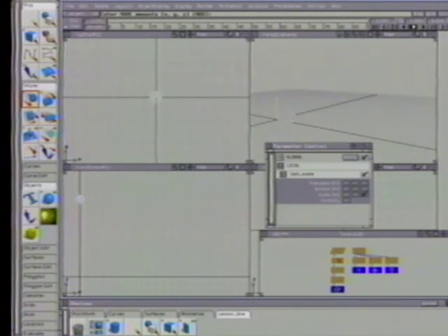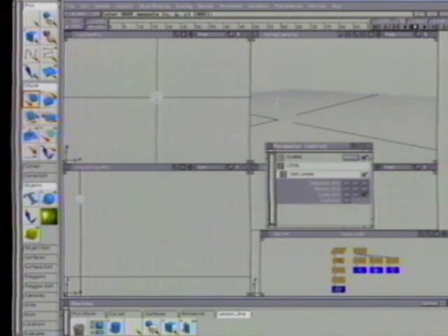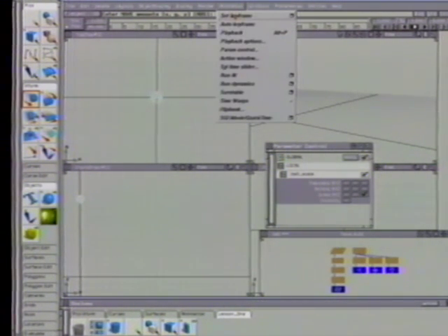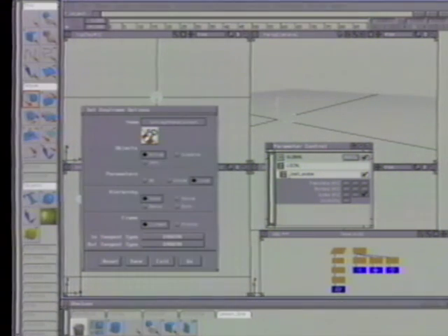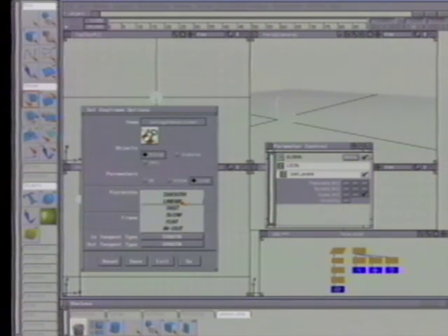Select Pick Object and click on the ball scale node in the SBD window. You can only pick middle nodes of hierarchies in the SBD window, or you can type the object name on the prompt line. Go to the Animation menu and open the Set Keyframe options.